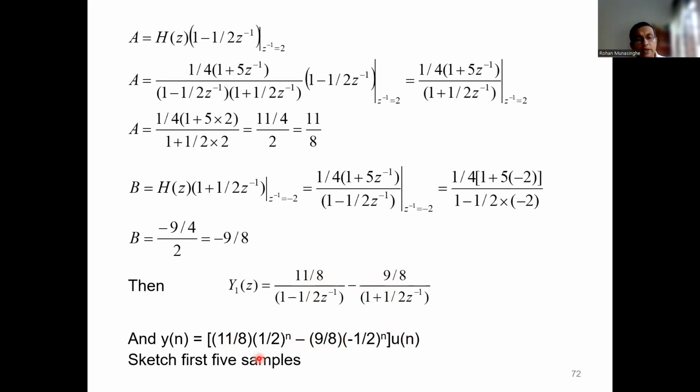So when you solve y[n] into a form like that, which is a function of n, the only unknown on the right-hand side is n. There's nothing else, no previous samples of y[n] or x[n] or anything. It's just a function of n. When you solve it to that format, we call it a solution, so that you don't have to program these, but you can substitute n equals 10, 20, 50, 30, whatever it is, and calculate your y[n].